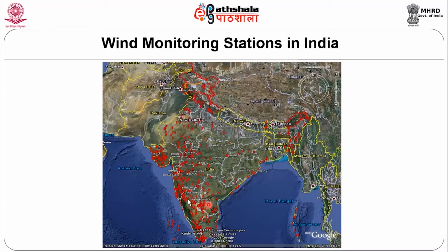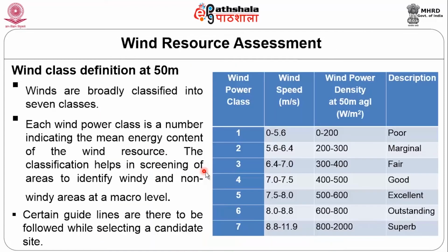All the data will come and get stored at the center point, and whoever wants to install wind farms can get the data from National Institute of Wind Energy, that is NIWE. The data over the years could be obtained, so that we can calculate the annual mean speed of that particular location, and if it is favorable, then we can go for the installation.